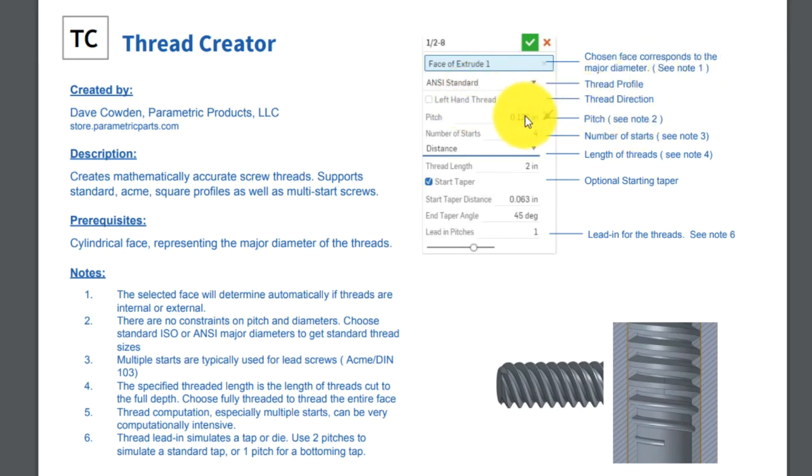Your pitch can be determined by yourself. When we apply it, because of the standards that we're using, we're going to apply these in millimeters, not inches. You can see here there's no constraint, so you can decide on the pitch, determined by the fixing that you'll be using, and also maybe by the tap that you're using to tap the hole, or the thread pitch if you're applying, say, a nut onto a threaded boss or feature.